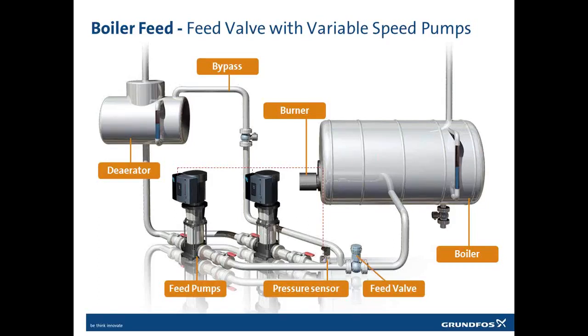But the question, again, as stated, is it okay to control the feed water pumps via steam header pressure? So I think what he's saying is that if we're monitoring the steam header pressure, the steam going out to the process, we use this as feedback to control the pumps. Yes, now I got it. No, we can't use the steam pressure.